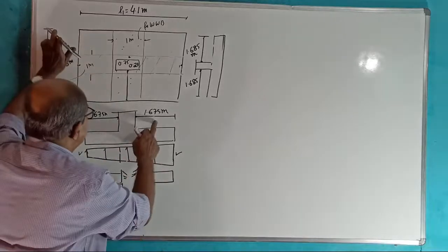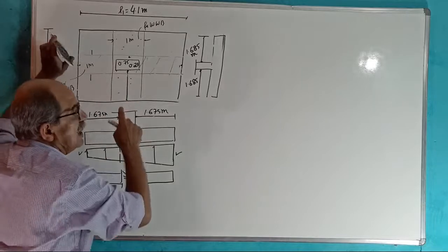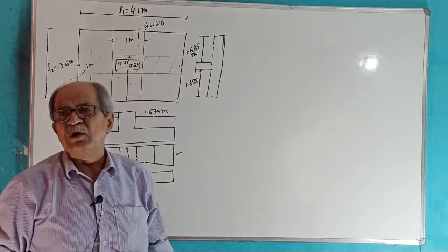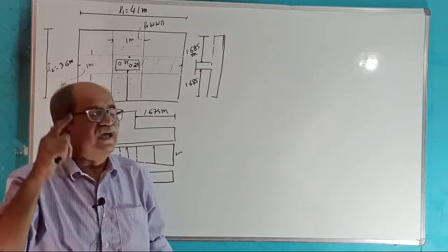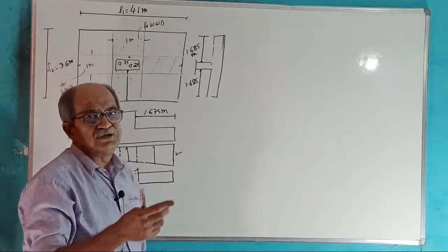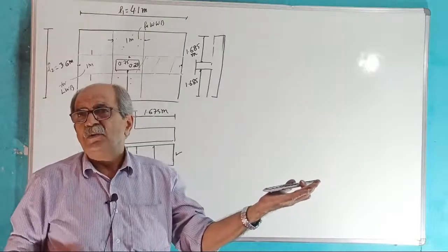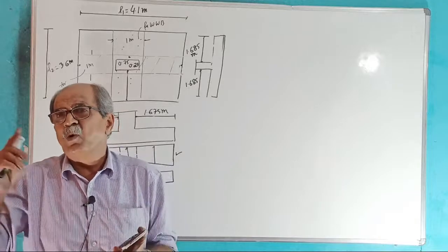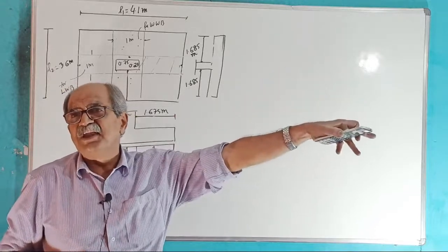If the distances are not same, that is the case if the column is placed a little eccentric, too much eccentric not allowed, little eccentric. Then I gave an example earlier. It is possible that where projection is more, pressure can be lesser. Where projection is lesser, pressure can be more. Then, based on projection, higher projection is critical.